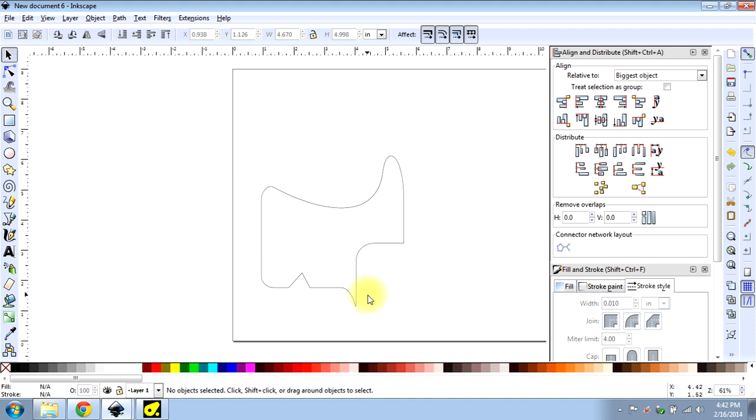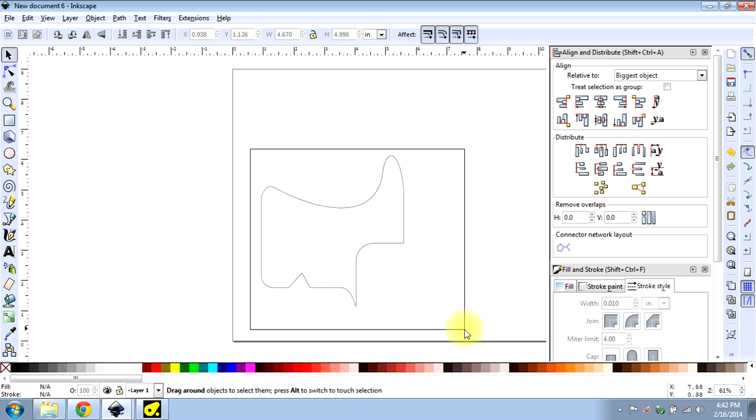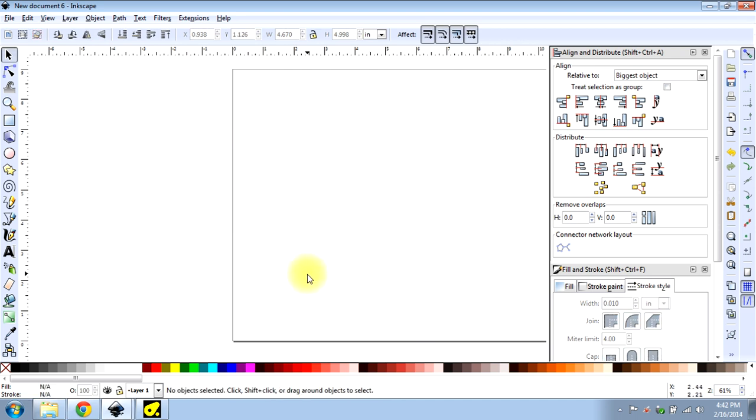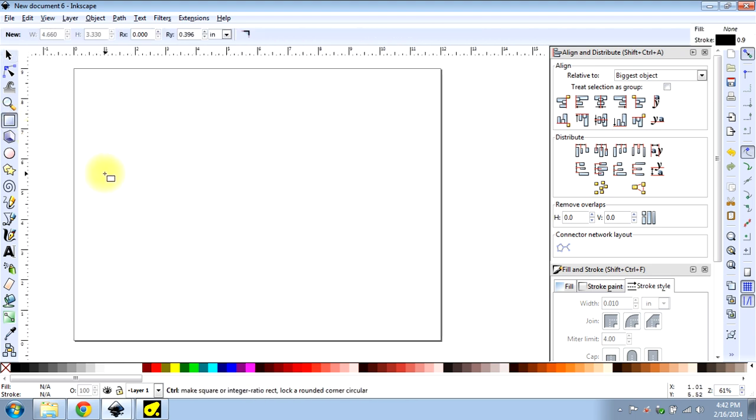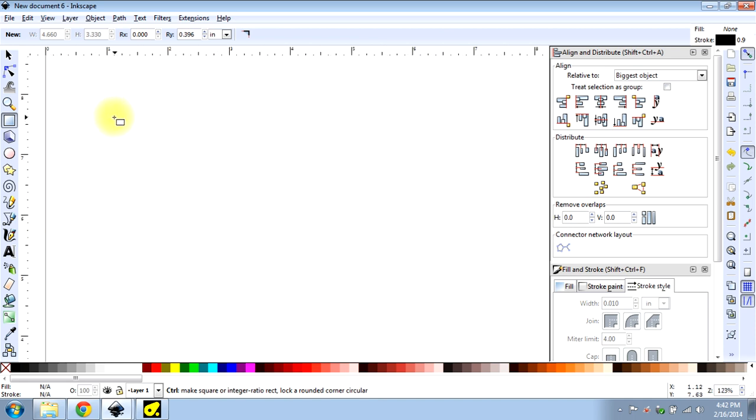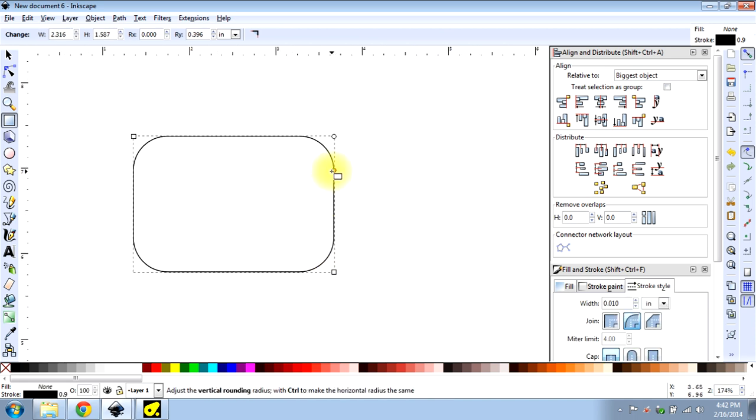So that's a quickie on breaking nodes apart. Shift B, Shift Control K to break things apart, in that order. Boom. Last but not least, we're going to hit this aligning stuff one more time, and we're going to show you how to build a box.